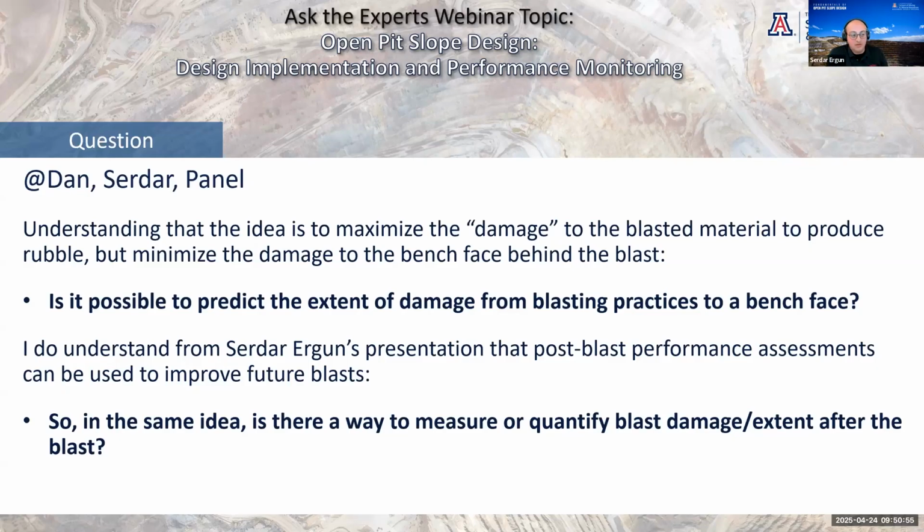And also we are using seismographs, which is basically seismic monitoring, vibration data during the blast with signature holes to understand how the production or trim blast is impacting the slope stability. And we also look into details such as P-wave velocity surveys to assess the reduction in rock quality or stiffness post-blast. And I know some other techniques as well that I don't think we're using at Bingham, like blast movement monitors. There are some hardware tools available for you to monitor the blast.